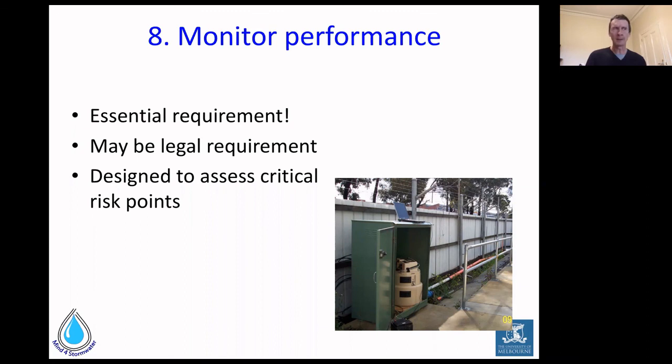Or a rainwater tank to say, oh, that's strange. It rained 10 millimetres, but according to the catchment area, only 2 millimetres of rain went into the tank. Perhaps the inlet is blocked, and to tell the owner that that's the case. And so really, if we're to see these systems be sustainable in the long term, we need to have ways of knowing when they're working and not, and monitoring is